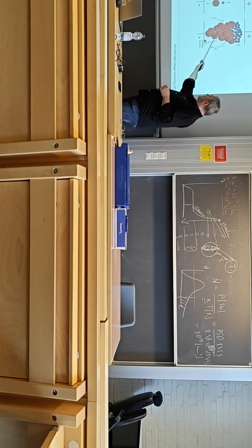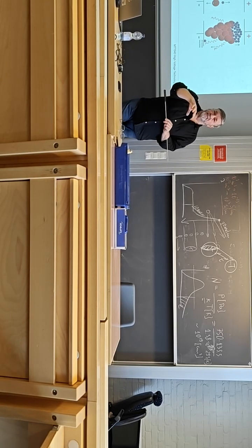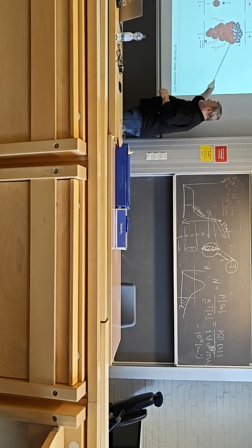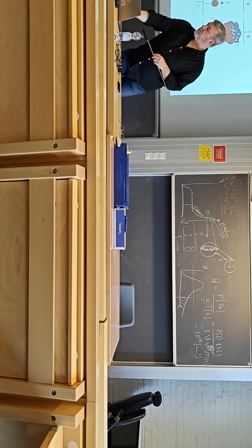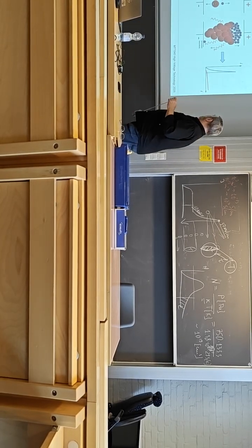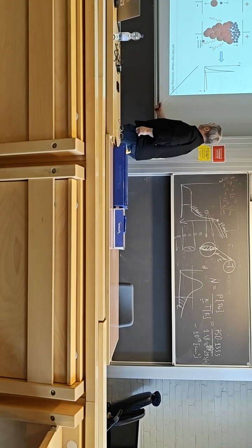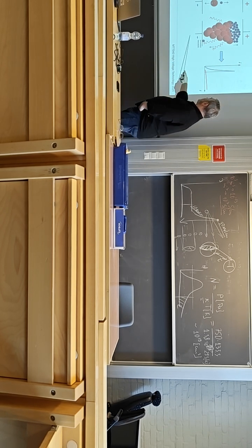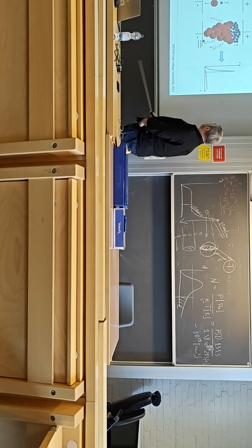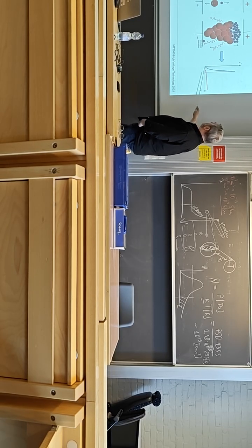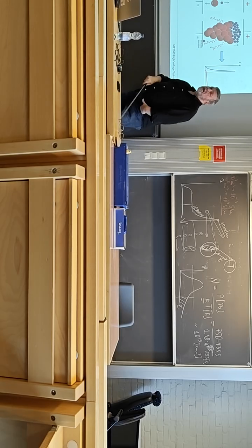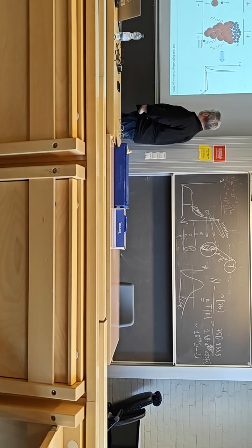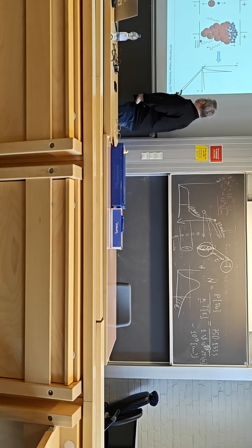Or the ions reaching the cathode also have some energy. If this energy exceeds the work function of the cathode material, there could be injection of secondary electrons by that mechanism. And as I mentioned already, when electrons reach the anode, you measure the external current. You just put a sensitive enough ammeter. You will get a very strong peak because of these electrons arriving at the anode, and then a quite slow increase of the current because of the ions coming.